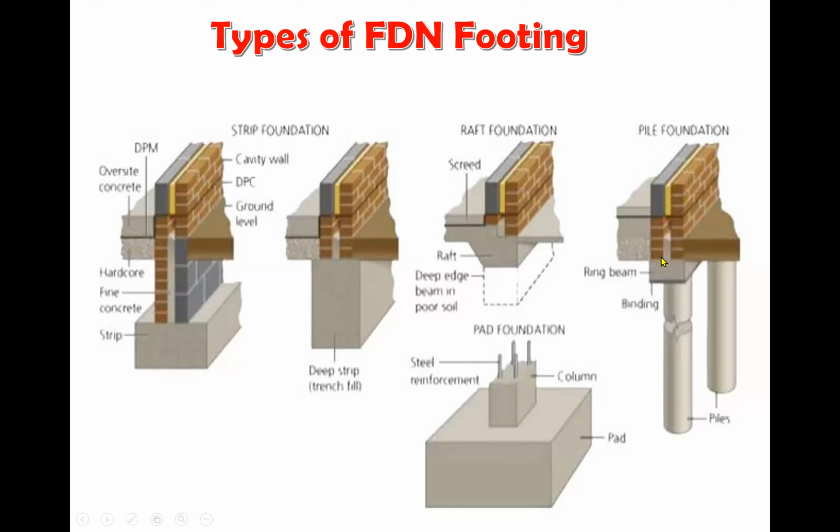And then you have the pile, which is recommended where you have a waterlogged area. So you have swampland or water along the coastal shore. You would drive piles until you get to firm strata. So all those buildings on the coastal shore, like down on the waterfront downtown, we have the Digicel building and BOJ and all those buildings, the foundations that would have been used for those buildings would have been pile foundations. So they would drive the piles all the way down into the ground through the water until they hit firm strata. They will be driving piles for maybe months before they can start building the building, because they have to hit some firm strata.